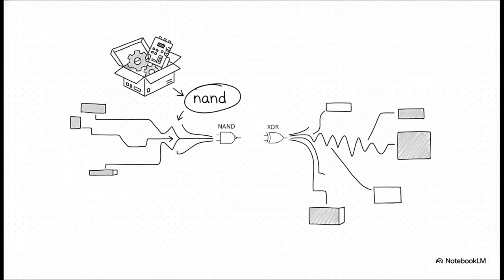And the exact same logic applies to slightly trickier primitives, like the NAND gate and the XOR gate. By just typing nand or xor, you're telling the compiler to reach right into its toolbox and pull out those exact physical logic structures. It's so cool because a simple, functional word in your code represents real, physical inputs and outputs sitting on the silicon.